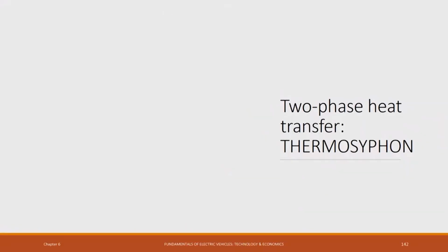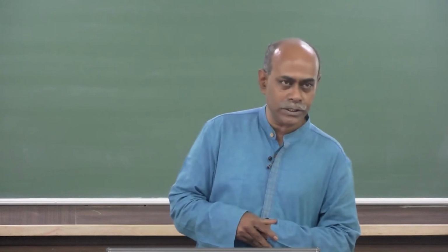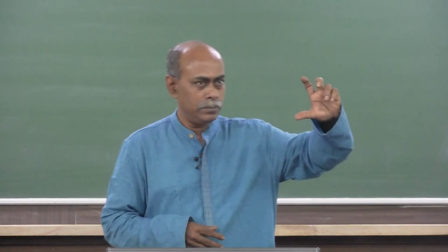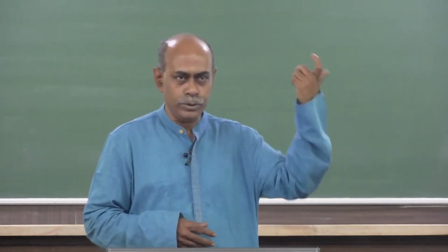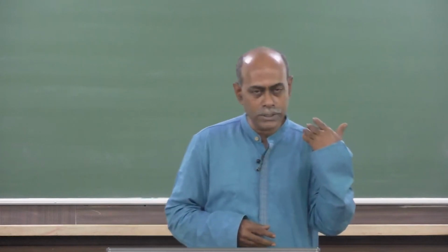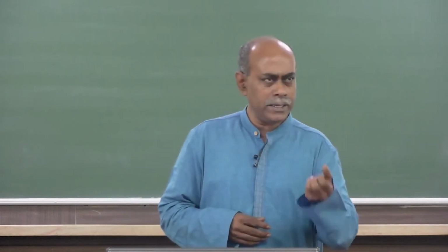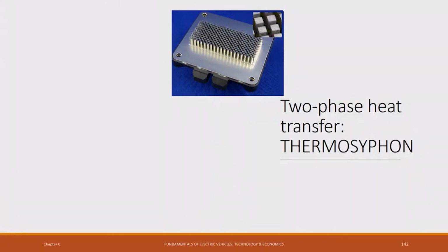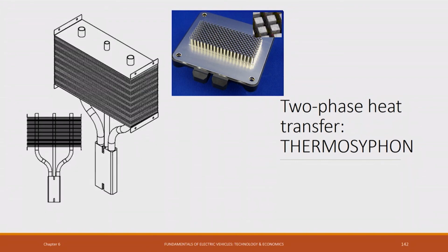Similarly, when we tried to work on the controller of a high powered motor, yes, the heat was higher. What made the job challenging is that the component generating heat is very small. It is just 4 inches by 2 inches, it is very small. So, not only is the heat high, but the heat intensity or the heat flux is very high, and normally you have to have very complicatedly machined components with high pressure liquid to remove all the heat.